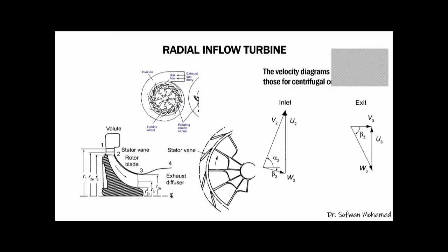Okay, other than a turbocharger in a car, the radial inflow turbine is also used in aircraft engines, and also in some industries such as natural gas processing, air liquefaction, or geothermal energy production. In automotive application, burnt gases from the engine exhaust manifold are directed into the radial inflow turbine of the turbocharger. Okay, a radial flow turbine usually uses a volute.